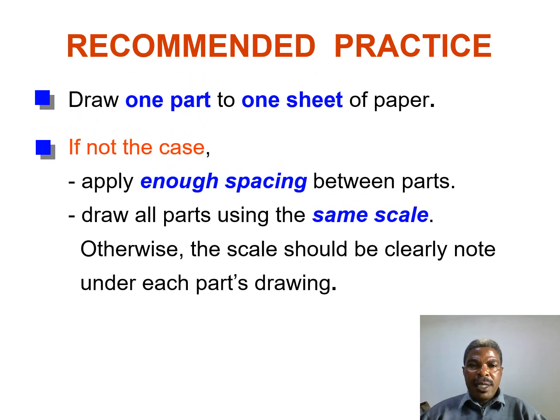So, recommended practice. You should draw one part to one sheet of paper, and if not the case, apply enough spacing between the parts. Draw all parts using the same scale. Otherwise, the scale should be clearly shown under each part of the drawing.